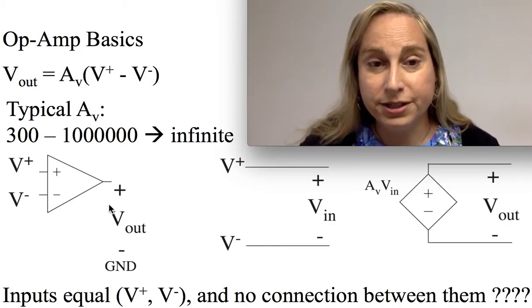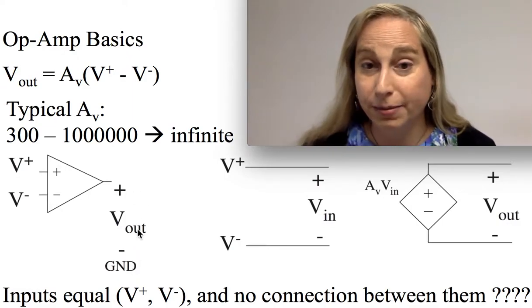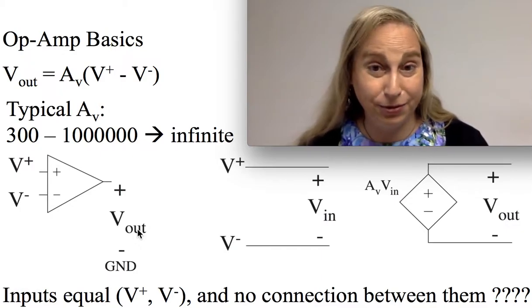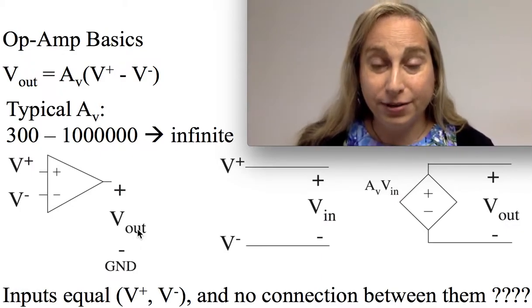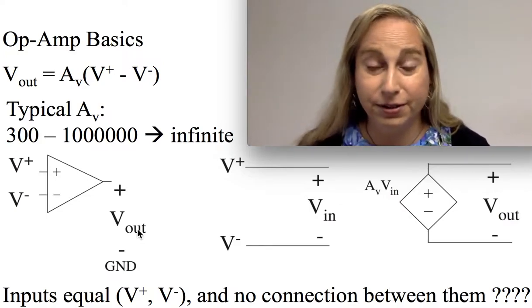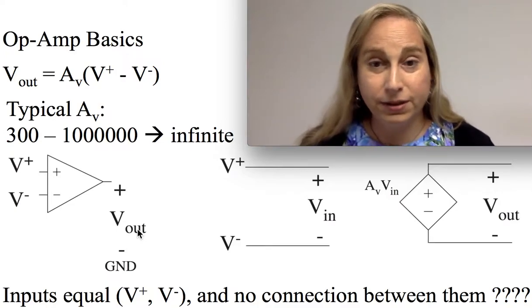This structure makes sense when the output voltage sits inside a power supply rail, because in the end you still have to power these things and you're not getting anything for free. You usually have power supply rails, maybe 0 volts and 5 volts, or 5 volts and minus 5 volts, and you'll notice this if you get hold of a discrete op-amp.